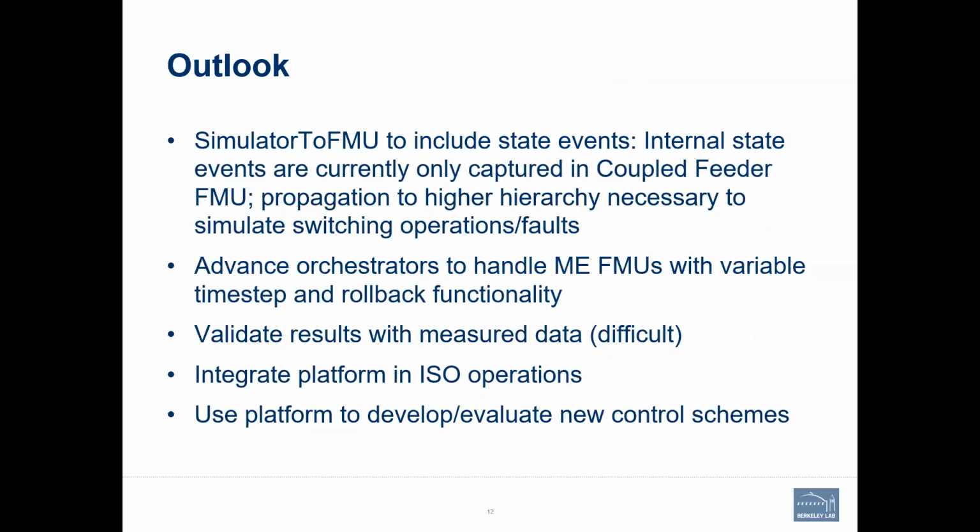Then, of course, advanced orchestrators to handle model exchange FMUs. I mentioned before, we use the co-simulation FMUs on the higher hierarchy levels, which also has to do with the state event handling. So that's definitely one improvement we want to do. Validating the results would be really good, but obviously difficult to get data for so many customers. But on the other hand, we did validate the individual models either in software, or actually some of the models like the inverter controller and PV generator. We actually validated in our test facility here at LBNL.